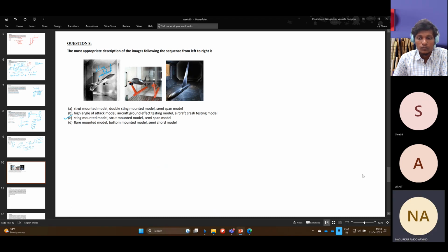Yes, there are three correct answers. It has been mentioned: to avoid large scale flow separation under the adverse pressure gradient, to increase the lift at low speeds, and effective tangential momentum injection into leeward flow. Okay, A, C, D. I agree, but B is also correct, to slow down the aircraft because the lift coefficient is increased.